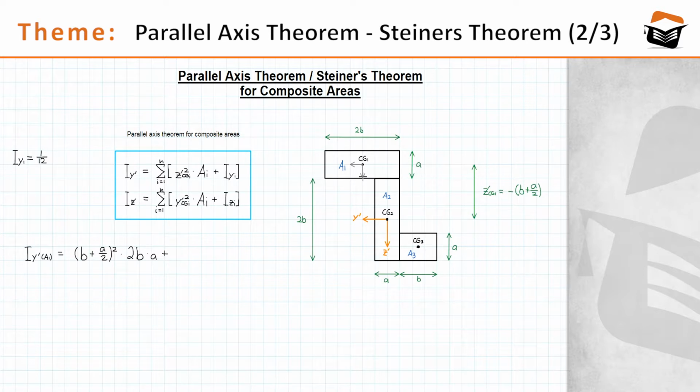That would be this one, with y1 and z1, just for convenience. And if you have an axis like this and you want to calculate the area moment of inertia of a rectangle, you have to attach the third power to the length that is perpendicular to the reference axis.